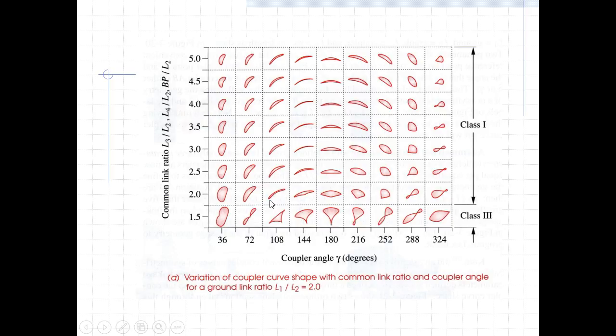And again, we need the length, which is normally given by R, and an angle to our coupler point, which was given by phi. However, if we are generating a linkage for a symmetrical coupler curve, in that case we only need 3 parameters: 2 link lengths and an angle. And we just saw that on our previous chart.